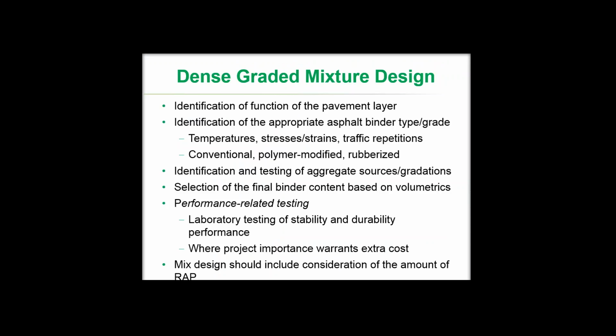The basic process of dense graded mixture design is to identify what's the function of that mix in the pavement layer. The point of this slide is to emphasize to the folks out there that a one-size-fits-all approach for mix design specifications is probably not the most efficient from a cost and an environmental point of view. If you have different uses in the pavement structure for different mixes, your criteria for the mix design are going to change. So the basic process is to identify that function in the pavement layer.